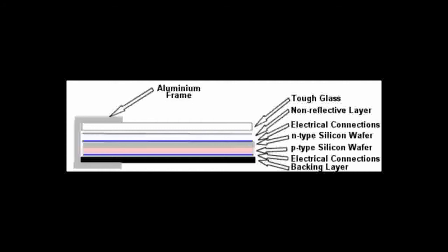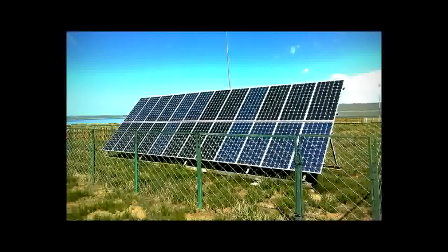And the industry standard warranty on power production is 25 years. You get that with all the framed modules, regardless of whether it's made by GE or Solar World or Sanyo. Thin film is a different animal. You only get a 20-year warranty. Right. It's sort of a newer solar product. But yeah, solar is robust, and owing to the fact that it has no moving parts, it has a very long expected service life. And so we say 40 to 50 years because the expectation is that the warranty period is only going to cover half the span of the equipment service life.